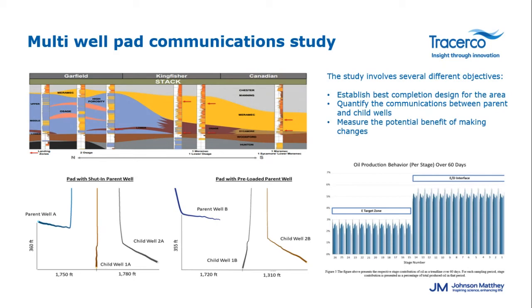One goal was to identify the production differences in 2 slightly different landing targets. Stages were traced in the 2 different targets, resulting in clear differences of higher production from the experimental zone than that of the in-zone stages. Those results are provided in the blue bar chart to the top right. The second and third goals concerned infill development practices, looking closer at well spacing, completions designs, and protecting parent wells.